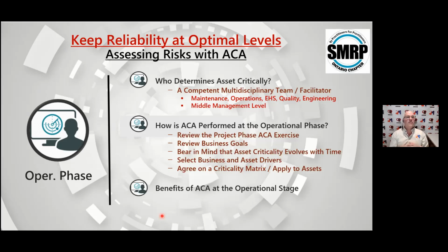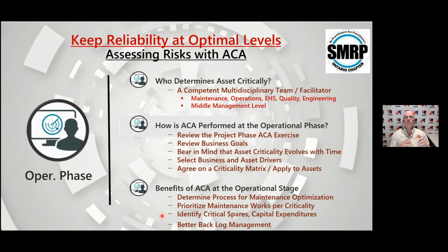So what are the benefits of doing so? Why do an asset criticality analysis? Why bother doing that? The benefits are numerous. So the first one is you will have a very good idea of what kind of process you need to develop maintenance tasks for your asset. Secondly, you will be prioritizing your day-to-day work with criticality in mind.